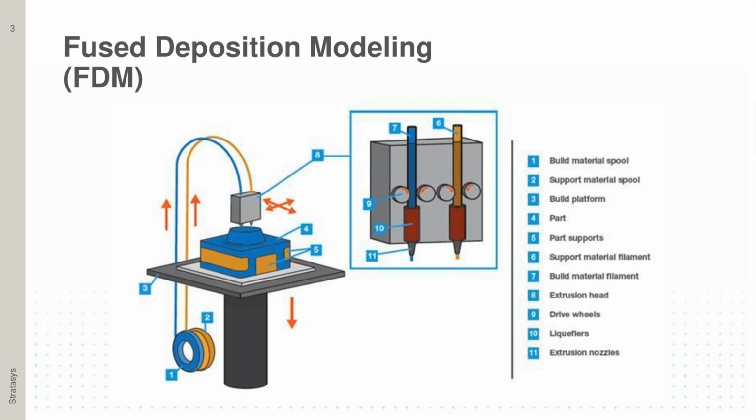The reason we deposit support material is to ensure that the part is dimensionally accurate and doesn't experience any overhangs or any areas where the material just can't build upon itself, as you see in the image right there. Once the part is done printing from the bottom up, the support material is removed either by dissolving it or physically removing it.